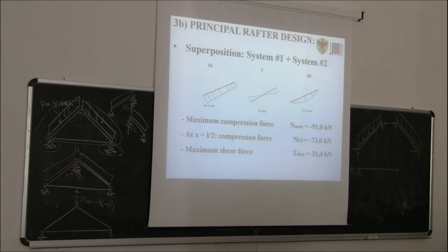Yes? Buckling will be included, if you remember. The buckling is included in this check that we are going to do for bending and axial force, because we need to calculate the sigma, and then we need to reduce the strength by this K factor that will take account of the buckling. So when we do buckling, we always have to choose one cross section. We said we check the cross section halfway, mid-span. This is okay because I have the maximum bending moment. We also have an important axial force, so it will be compression, coupled bending moment and axial force.